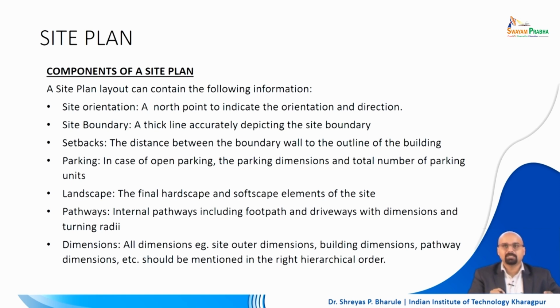The dimensions, the orientation, the boundary, how much is the distance of the boundary from the main street, how 2 different boundaries or 2 opposite boundaries of the site vary from each other in terms of level, in terms of distance, in terms of angle, dimension, the kind of setbacks that are to be followed as per the municipal corporation or as per the rules that are being followed for that particular area, right.